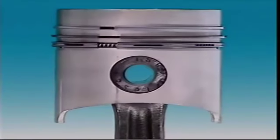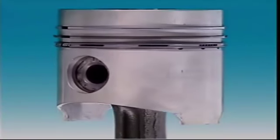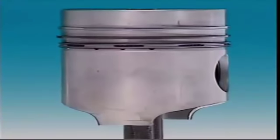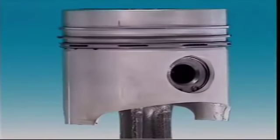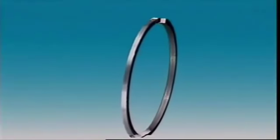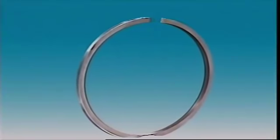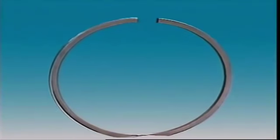New rings and cylinders have minor irregularities, and when these wear off, the rings will make a better fit. To help this along, the rings can be given a porous coating. It's softer and wears more quickly than the ring material, which is usually cast iron. To prevent wear, the face of the piston ring can be coated with a harder material like chromium that operates well against cast iron without scuffing.